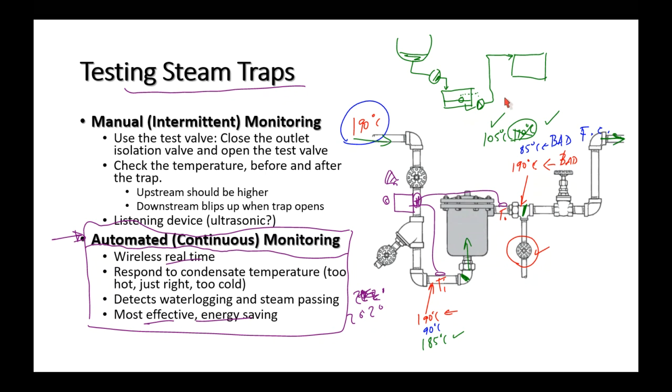And that would be in the powerhouse. And so maybe we've got a whole bunch of condensate tanks with their own little pump, and they all pump back into this main condensate tank. This one here is big, right? This one here might be, I don't know, 10,000 gallons or something like that. And then there usually would be some sort of a level control, and we may actually put our makeup water into this condensate tank.